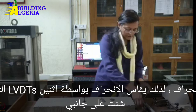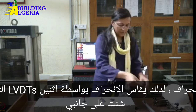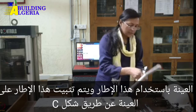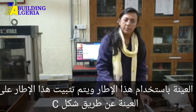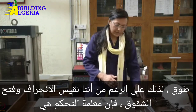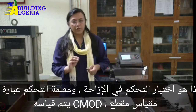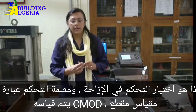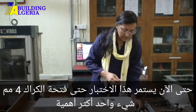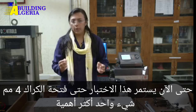Deflection is measured by two LVDTs, which are mounted on either side of the specimen using this frame, and this frame is fixed onto the specimen by means of a C-shaped collar. So although we are measuring deflection and crack opening, as this is a displacement control test, the control parameter is the clip gauge, CMOD, which is measured by the clip gauge. This test is continued until a crack opening of 4 mm.